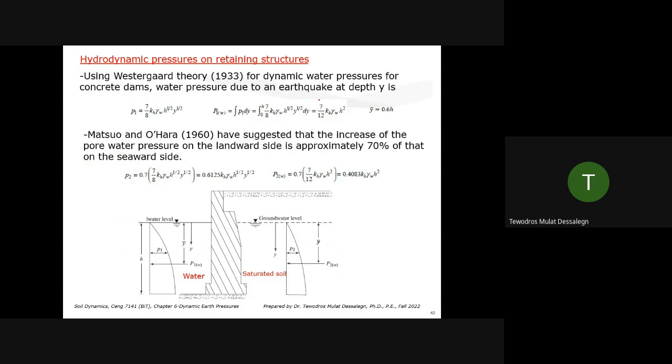Is that clear? At least make sure you understand theoretically what we are doing, how we are incorporating the dynamic forces. This is still a pseudo-static approach. We are using representative accelerations, right? A single value of acceleration, maybe the peak value. If we are doing a full time history analysis, at a very small delta t, we pick the corresponding acceleration. When we finish that, then we pick the next acceleration, and the next. It's very time-taking.